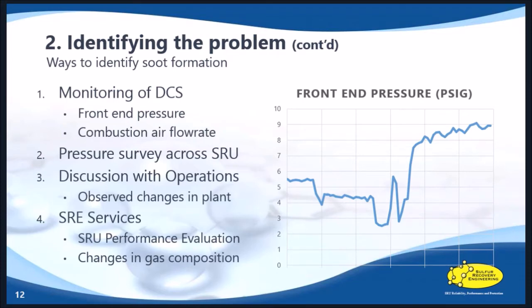Acid gas is going to the front end. With respect to the caveat, your ADA needs to be properly calibrated and well maintained. If that is the case, and you're fairly certain that it's measuring the H2S and SO2 numbers properly, over time you'll notice that if your acid gas composition is changing, the total combustion air will slightly change as well. This is a great way to notice something on the DCS, and another item to monitor.